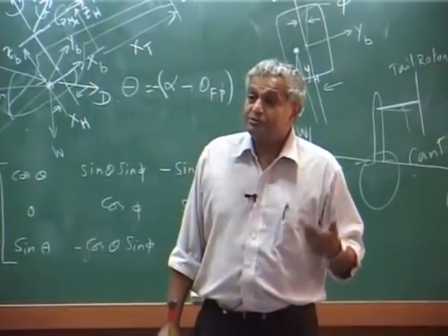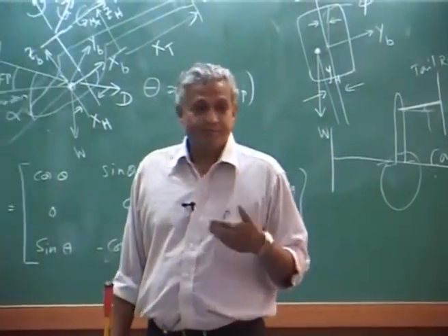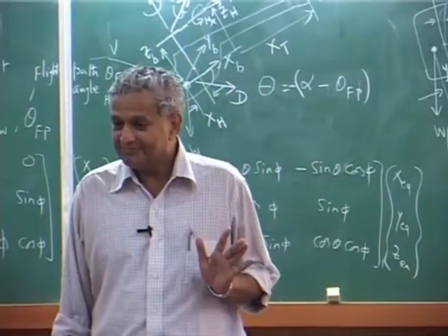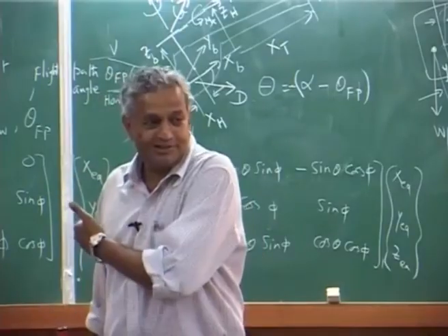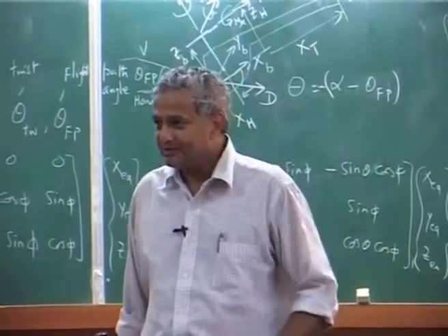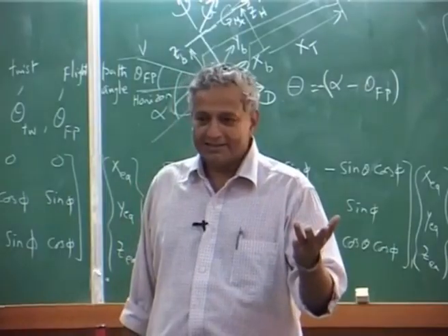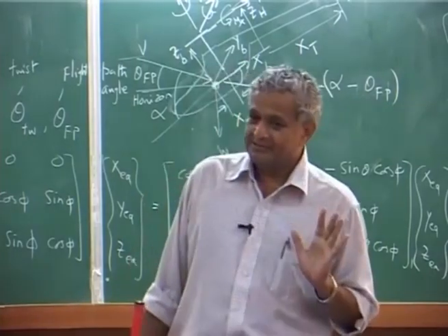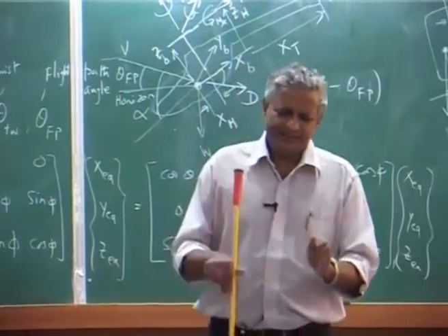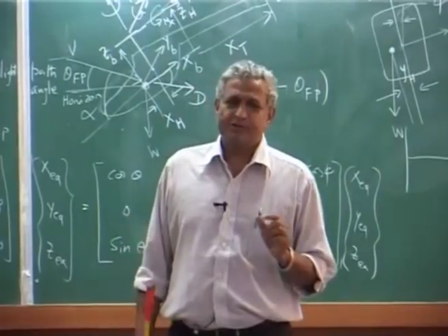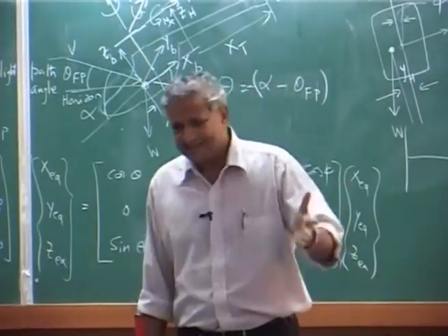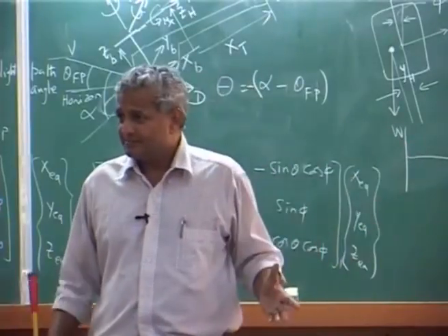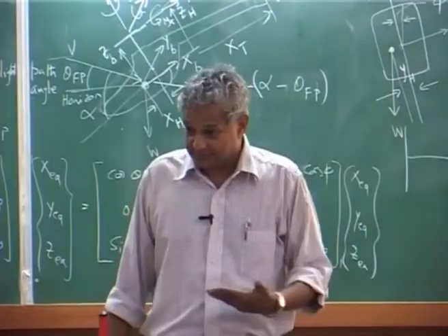What are the 2 unknowns you throw? Basically you throw the roll angle, and the tail rotor is thrown. That means 2 unknowns are thrown, remaining are theta naught, theta 1c, theta 1s, and alpha, that is all. But that is for a research publication where you want to study more about only blade response, blade characteristics, the influence of certain geometry on the aeroelastic behavior. They do not do a full analysis of the helicopter.